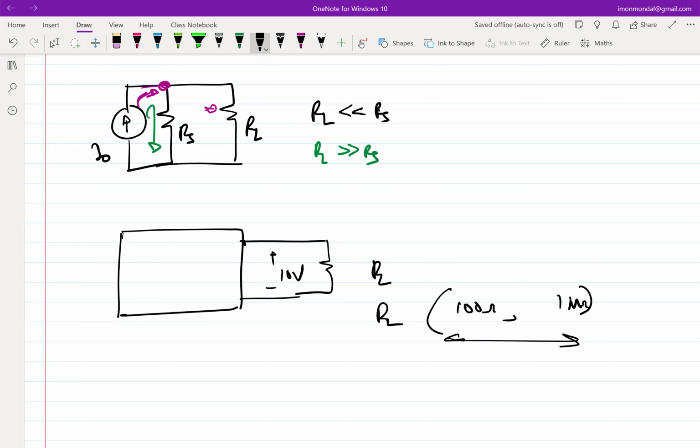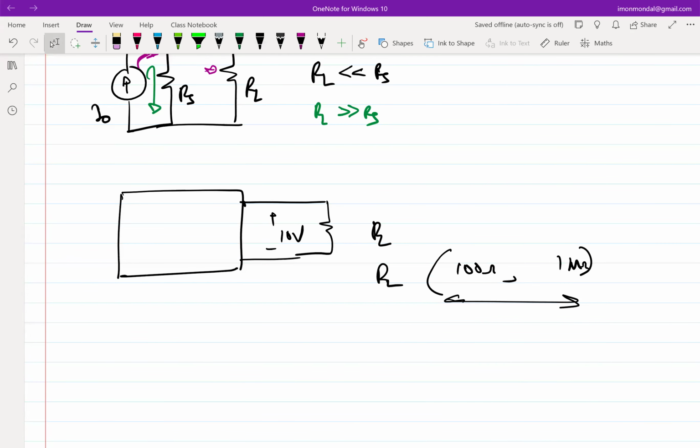So now we all understand when we say internal resistance, it is a voltage source and some series resistance and so on. But there is a different term that we normally use in circuit design. The resistance which essentially we are looking at is the resistance looking into the port, and that essentially is the Thevenin equivalent resistance.